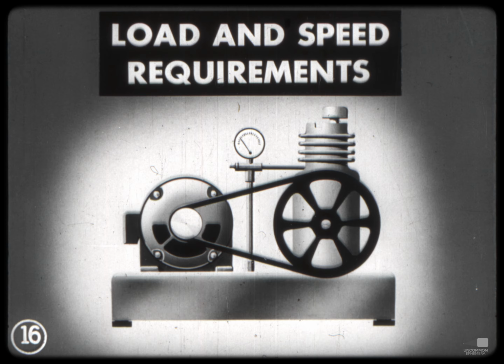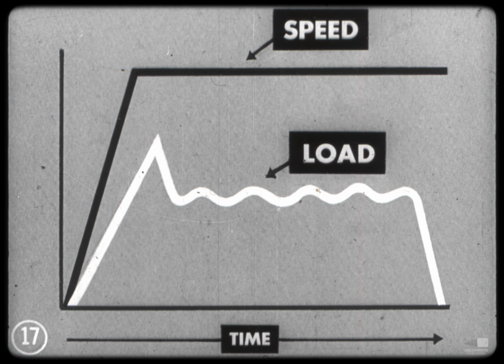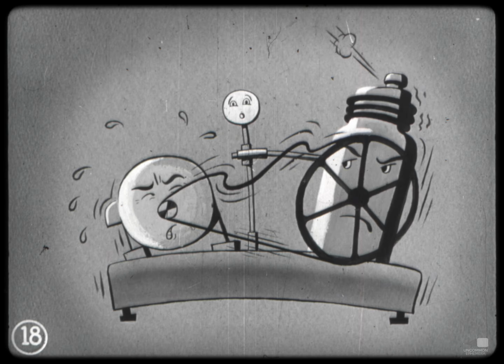From the duty cycle of this compressor, for instance, its steady speed of operation indicates that a constant speed motor is needed, while the load carried shows what horsepower and running torque the motor must have to carry the load. In addition, when it's known whether the compressor starts loaded or unloaded, then the starting torque can be determined. Also, the frequency of starting and the time it runs continuously show the time rating the motor should have.